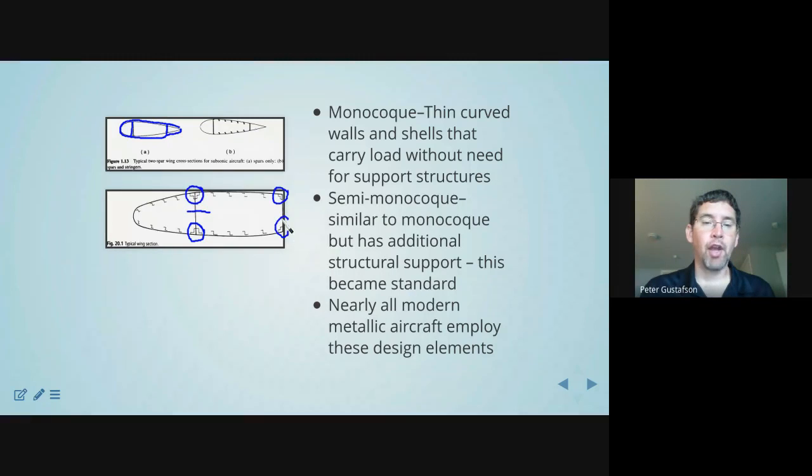There's the spar caps. You have localized reinforcements. That's these here. Those are essentially little mini beams that take the pressure from the skin and help carry the load associated with that pressure, ultimately towards a rib, and then from the rib to the main spar.